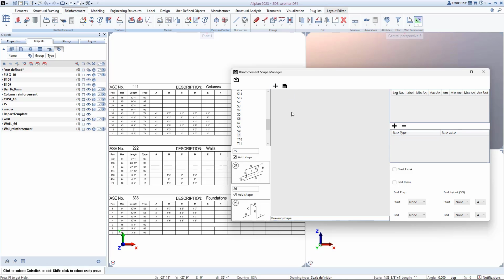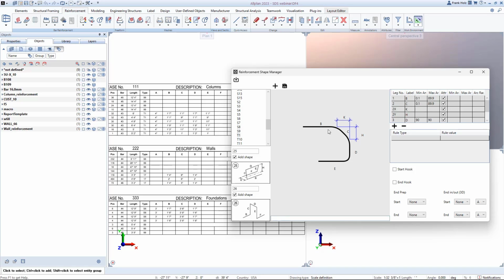Adding a shape is extremely easy. I basically get to draw a freeform shape of bar. If I hold shift, it's going to lock it to the 45s. And it's automatically going to add some of the most common dimensions and nomenclature for us. I right click, it's going to complete the creation of the shape. I can see that I did all acute angles, so it's doing 0.1 to 89.9, but I could easily get rid of this and then it would have no requirement in that kind of way.